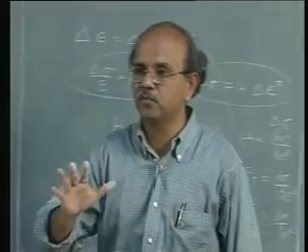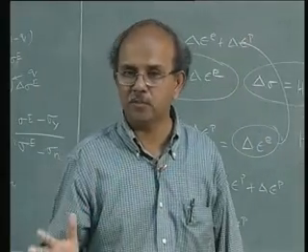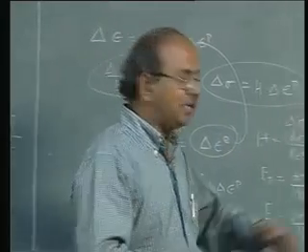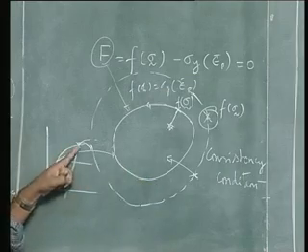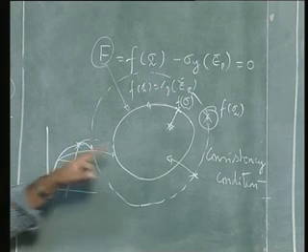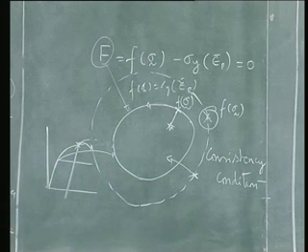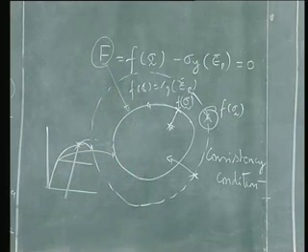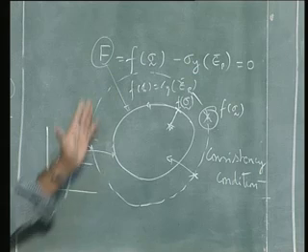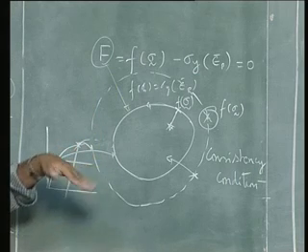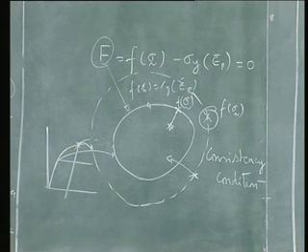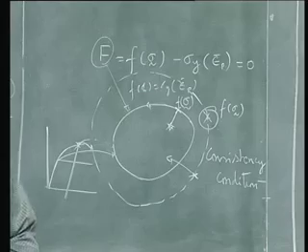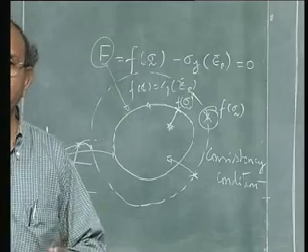Okay, it's an irreversible dislocation, motion and slip are irreversible phenomena, and so I will leave the yield surface there as I had left the yield point here. Okay, I will come in. This is what is called unloading. So, you see that there are three types of things that are possible. One is loading, another is neutral loading, and the third is unloading. Neutral loading is especially important in the case where we have perfect plasticity.